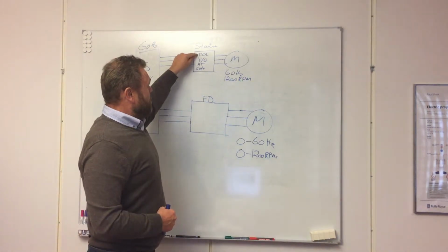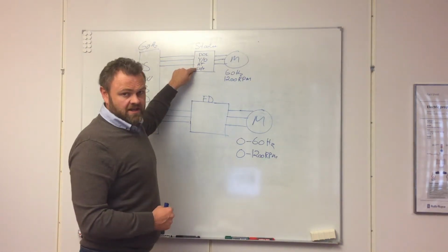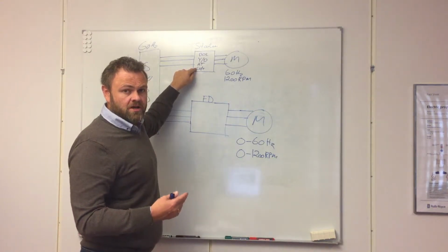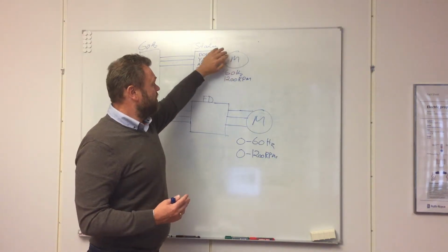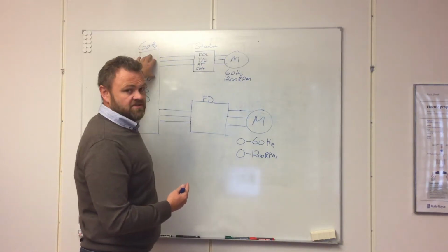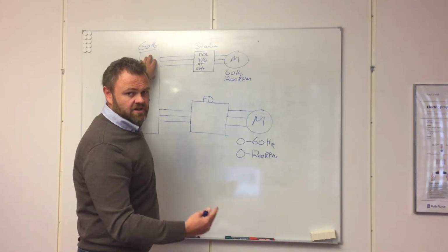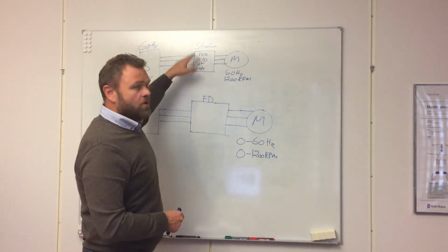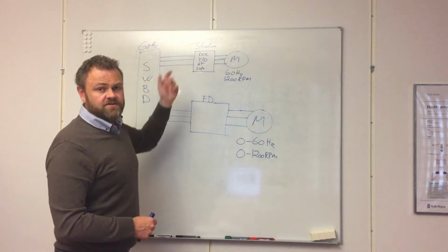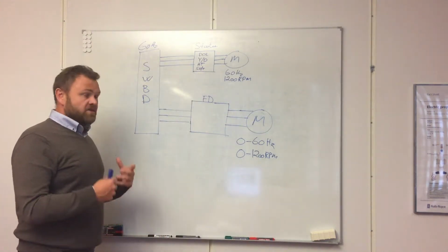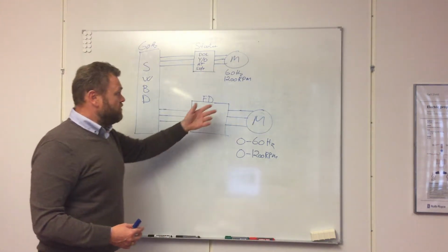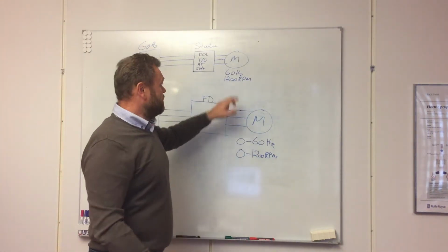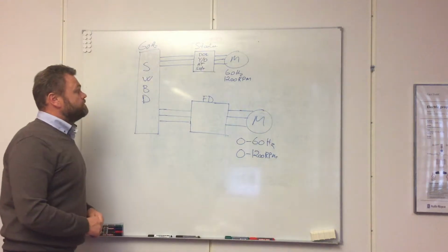Because all these ways of starting the motor will connect the motor directly to the 60 Hz after the starting sequence. So no matter which of these starting devices you pick, your motor will run at fixed RPM throughout all the duty.